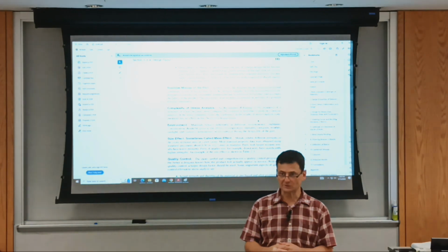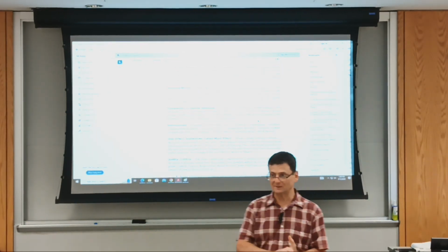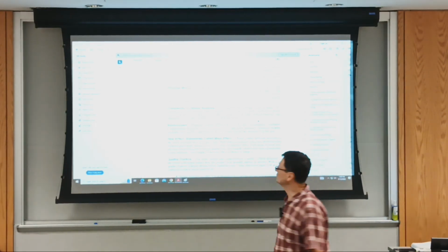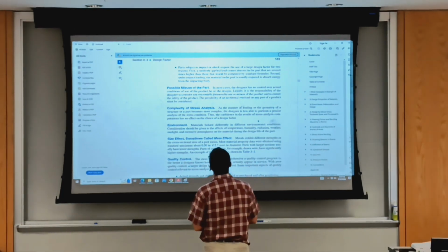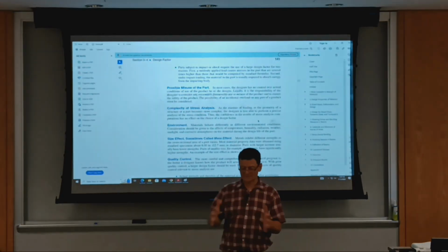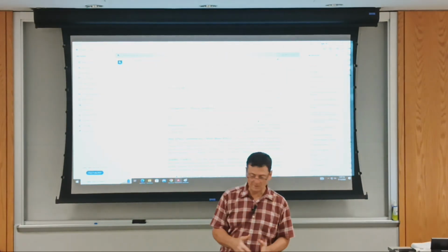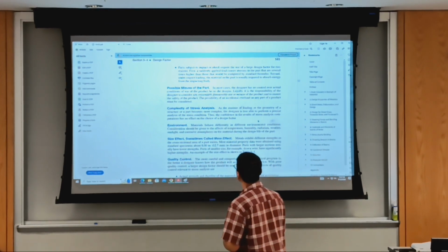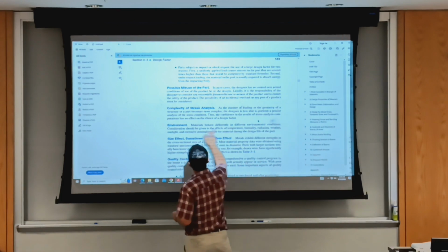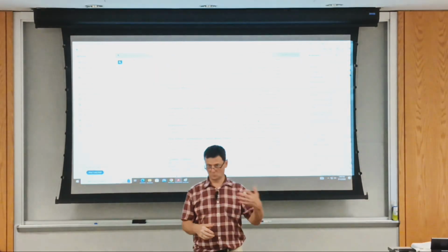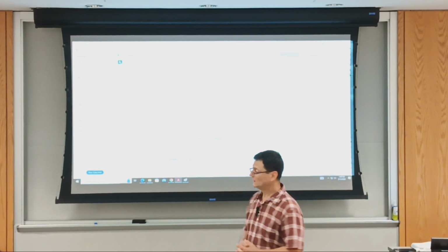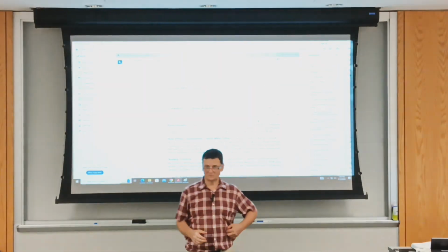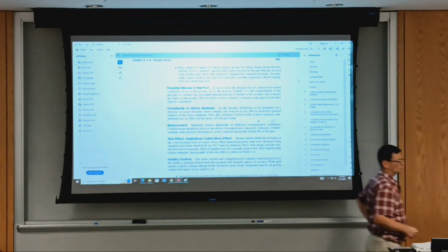So what do you say? Engineers approximate a horse with a sphere to make the math easy. You approximate a rather long part with a continuous beam, but it might not be. A beam in bending has to be rather long, but we approximate and use the beam theory for short beams like teeth in a gear in a first approximation. And then you can have, after or during its use, environmental effects. Corrosion can weaken, and it can create places where a fracture can develop and grow into a full fracture.